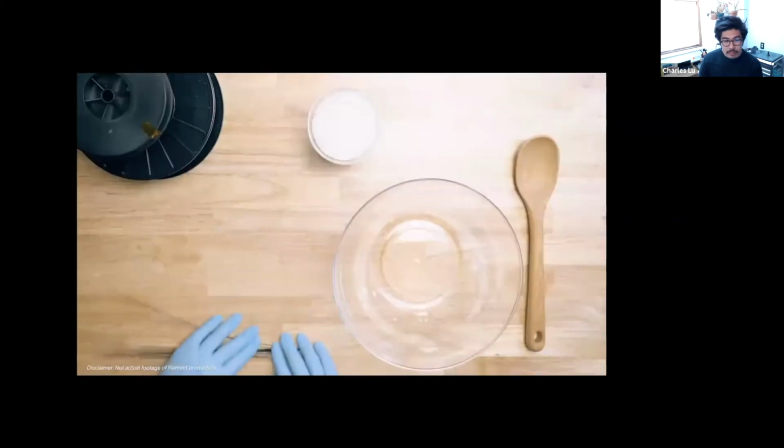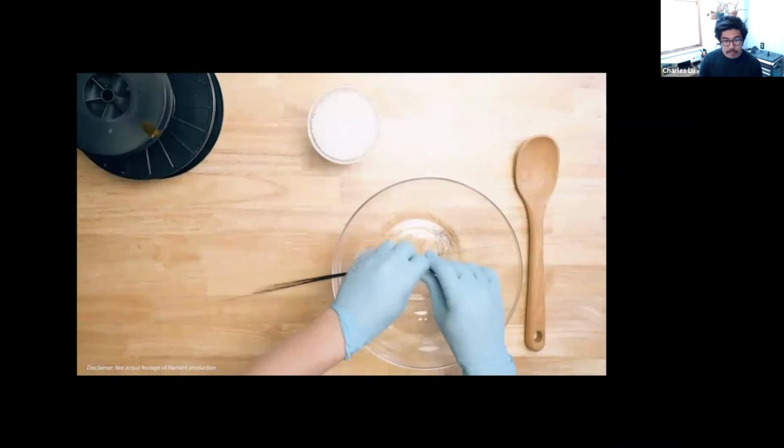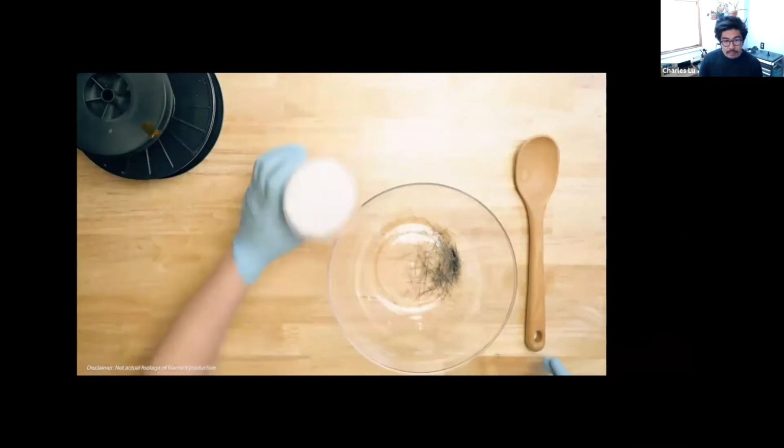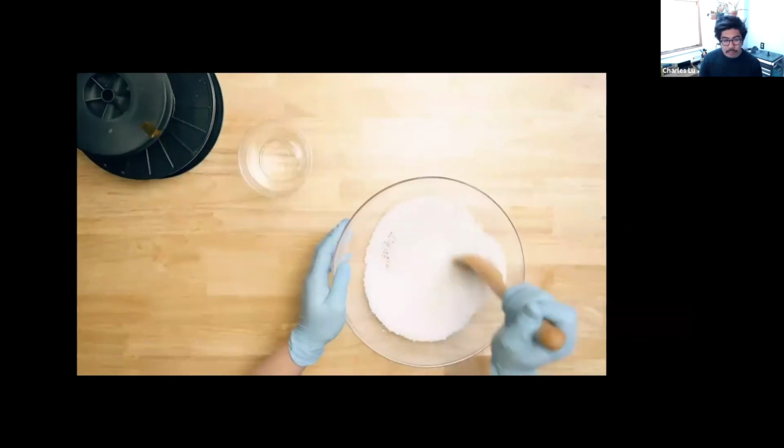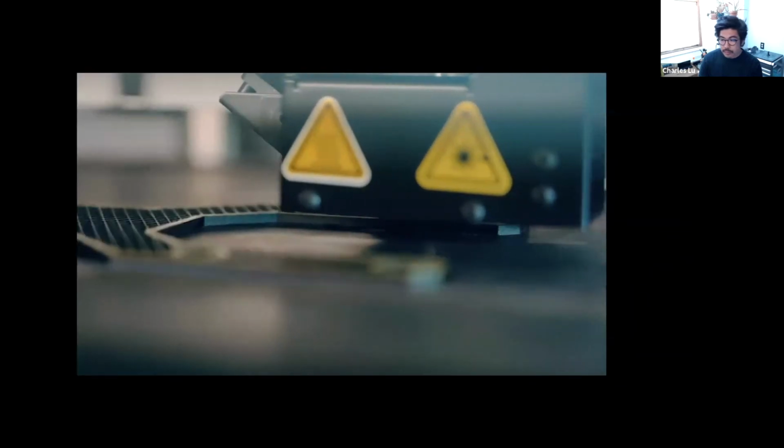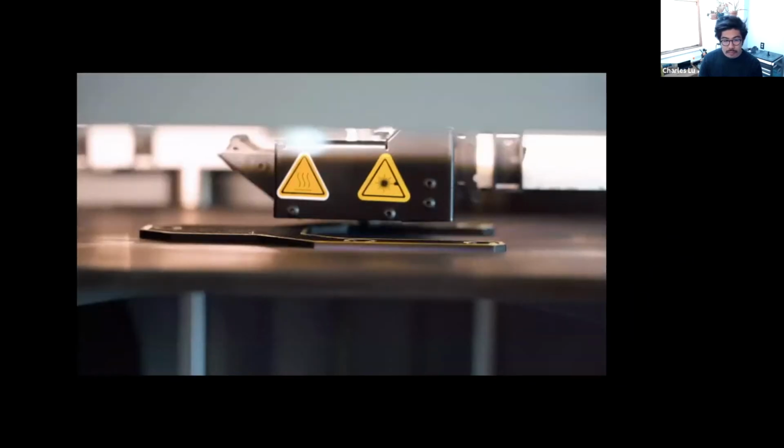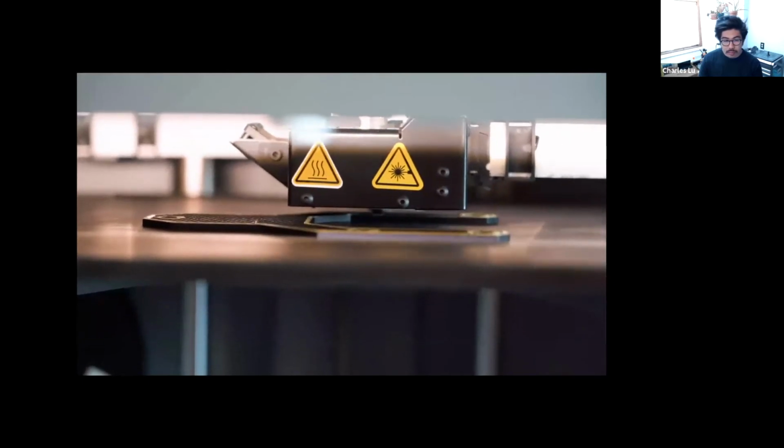So chopped fibers in 3D printing are a bit different, referring to small bits of carbon fiber broken up and mixed into a thermoplastic like ABS, PLA, or nylon. This gets extruded into a spool, which can then get 3D printed with a deposition-based printer, but doesn't leverage the continuous strength of those fibers. So it's sort of like a booster pack for standard 3D printing thermoplastics. It bumps up some of the material properties like heat resistance, strength, and stiffness, and may improve the print quality and dimensional stability as well. But the strength is largely defined by what's holding it all together, which is the thermoplastic.